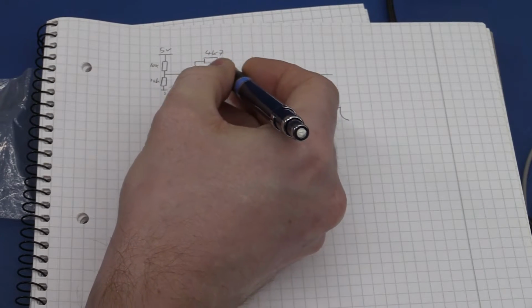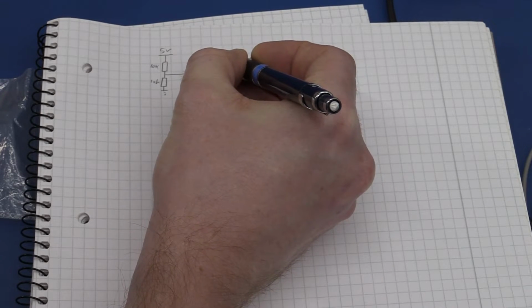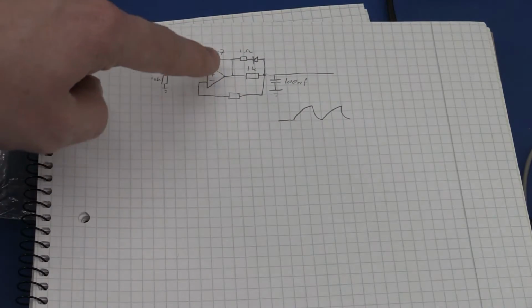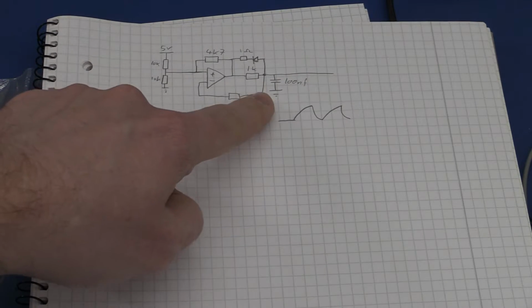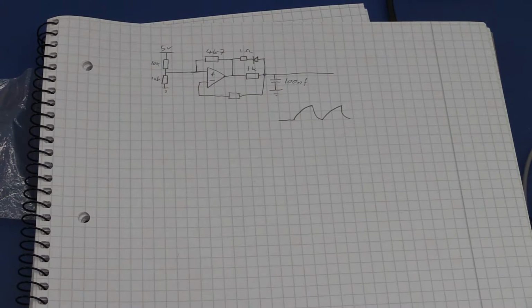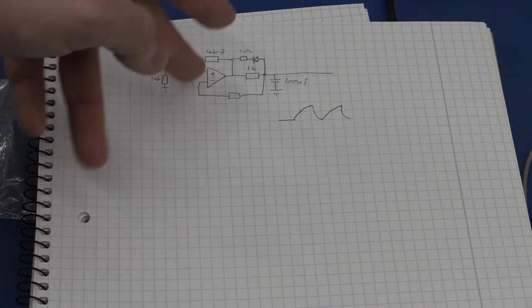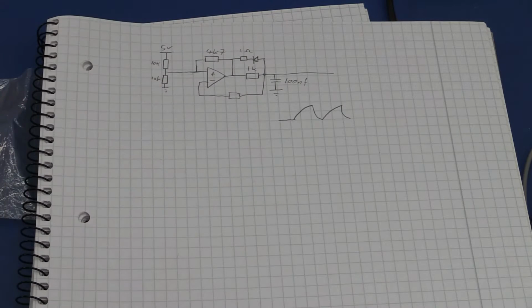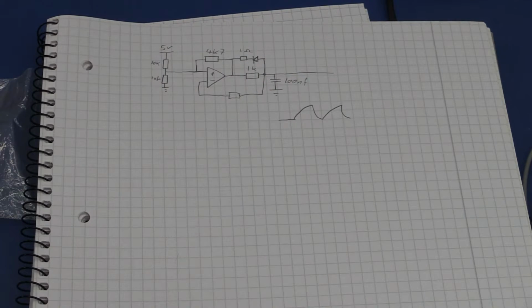If we want to be kind to the op-amp, we would add a little bit of resistance anyway, say just like 1 ohm something, so we don't directly short the output into a capacitor. The capacitor is, in theory, able to deliver infinite current over a very short period of time. It has ESR and things like that, and most op-amps are protected so that you cannot destroy the output anyway, but it's good practice to put it there.